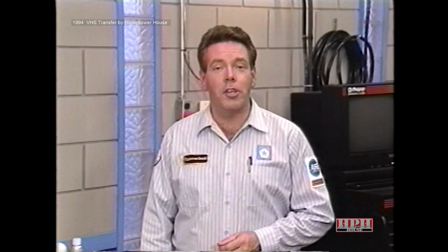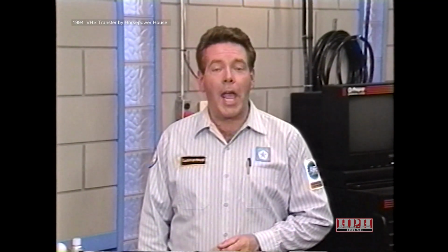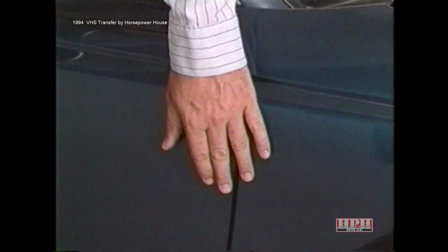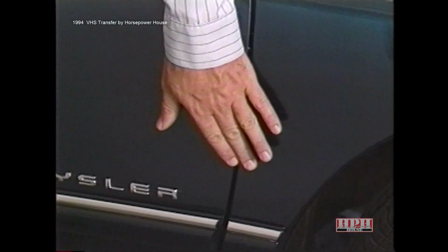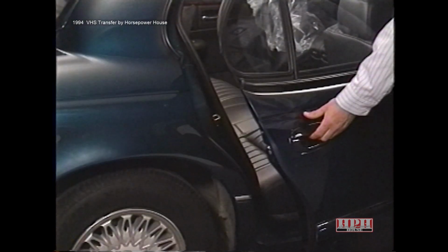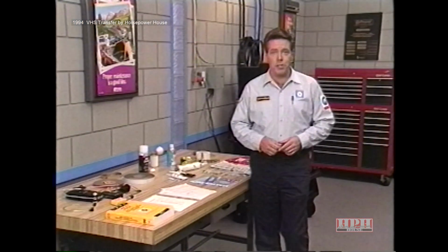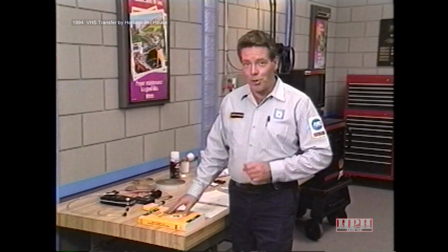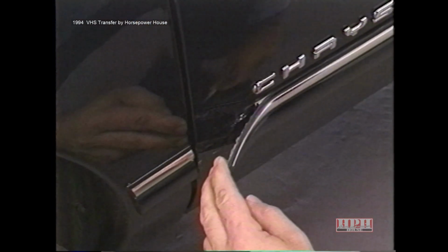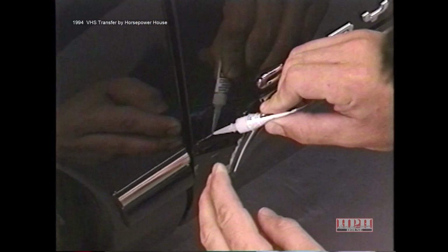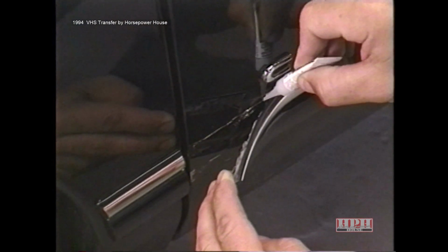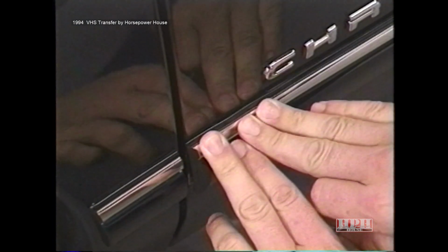If the customer's description indicates turbulence, look carefully at alignment and fit, especially around the doors. Ideally, the front edge of the door should be flush or tipped slightly inward of its mating component. The rear edge of the door should be flush or slightly outward of the rear mating surface when tightly latched. You may need to adjust the door hinges or door latch striker if the doors are not aligned properly. See your service manual for details. Turbulence may also be caused by loose trim pieces or moldings. These should be reattached using an appropriate adhesive.